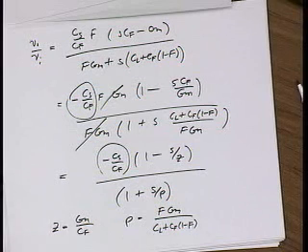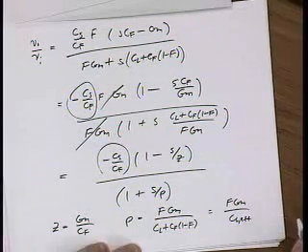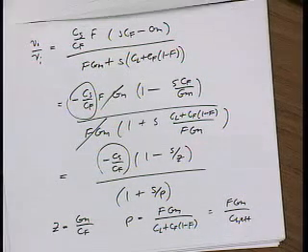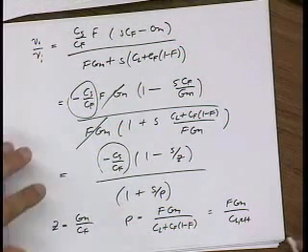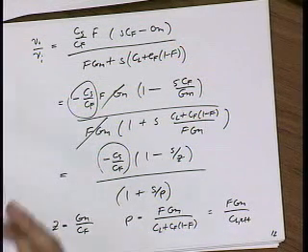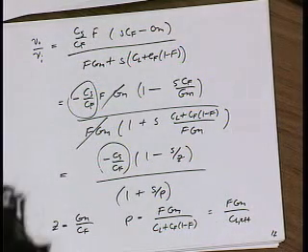What about the pole? Does the pole make sense? So I might write this as FGM over CL effective. First of all, does it make sense that the pole frequency is F times GM over CL effective, based on your background in frequency response of feedback amplifiers? Yes, it makes perfect sense. GM over CL effective, that's the unity gain frequency. Homework number 2 or 1, you guys calculated unity gain frequency. And if I apply feedback, the bandwidth should improve by the loop gain. So yeah, this makes perfect sense.